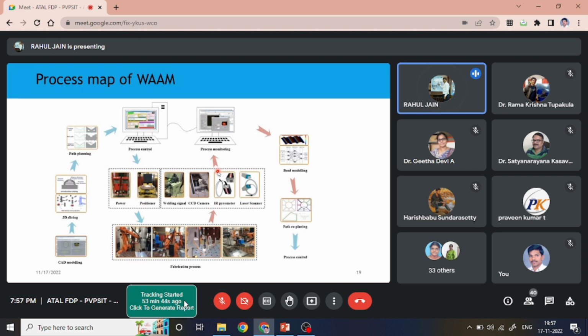For example, based on our past experience, we know that if we increase the temperature, the melting rate will increase. Based on this, we found that the electrode is not melting properly, because of which you are getting a particular type of defect.